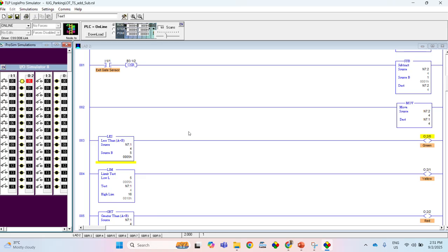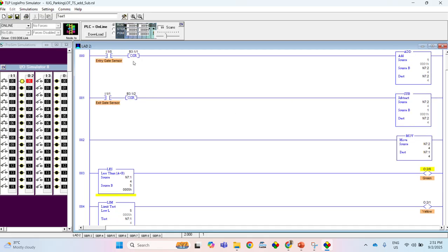As I have shown you, you can use the same counter up or counter down, or you can use addition and subtraction for the same purpose. But if you use addition and subtraction, you must use a one shot register. Another thing you have to remember is that you have to use two, B3:11 and B3:12 internal memory, as one shot registers. The one shot register instruction is located here, bit under bit, you can see OSR, and you give the address. For two different rungs, you have to use two different one shot registers.